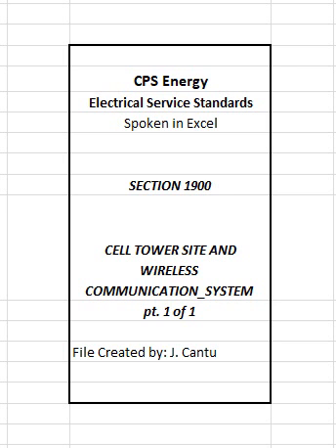1903 Existing service installations. Where an existing service requires an upgrade or redesign in order to supply an additional tenant's meter loop(s), customer will be required to modify service in order to comply with one of the methods described in Article 1902 for new services. Where an existing 3-phase service requires an upgrade or redesign to accommodate a single-phase tenant, the single-phase customer will be required to modify the existing service in order to comply with Article 1902 to serve their load.